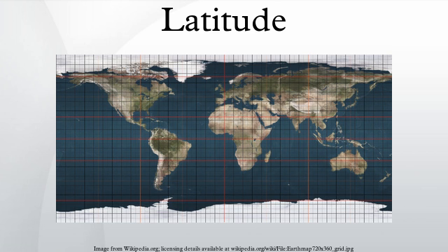Geodetic and geocentric latitudes. The graticule on the ellipsoid is constructed in exactly the same way as on the sphere. The normal at a point on the surface of an ellipsoid does not pass through the center, except for points on the equator or at the poles, but the definition of latitude remains unchanged as the angle between the normal and the equatorial plane.